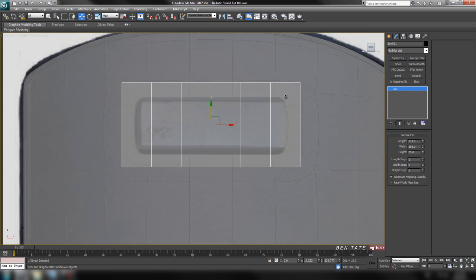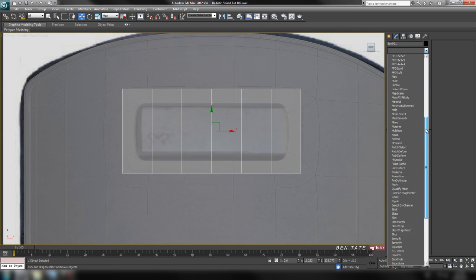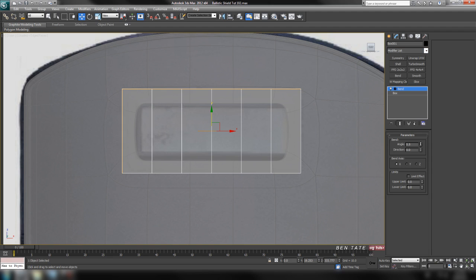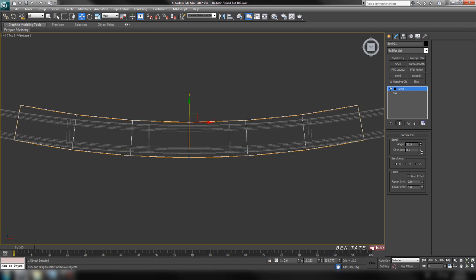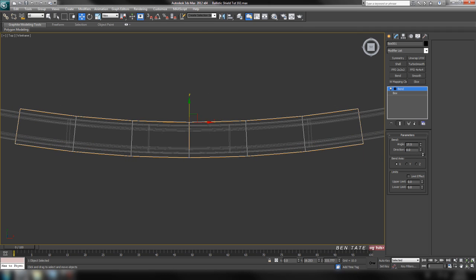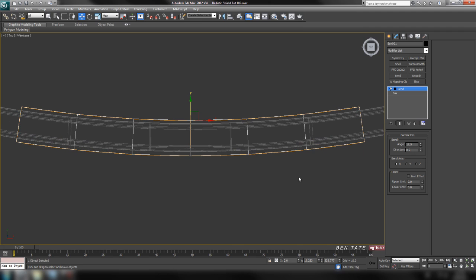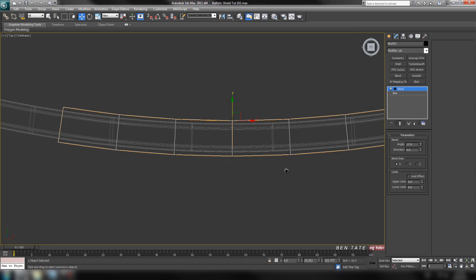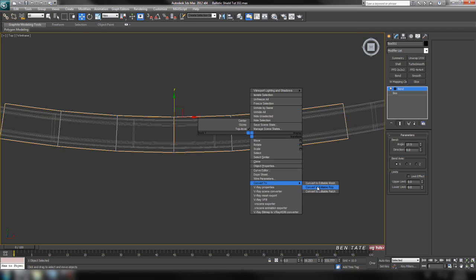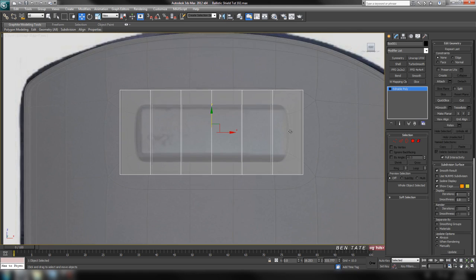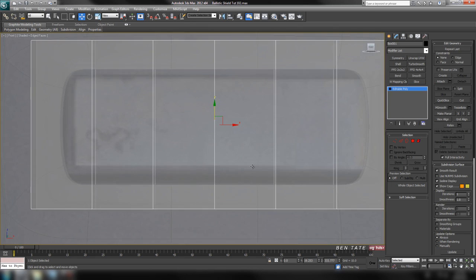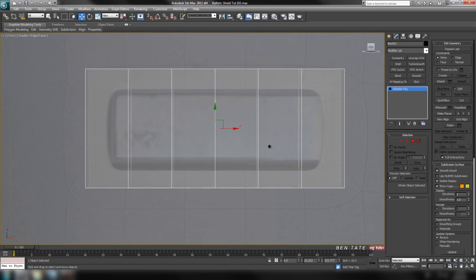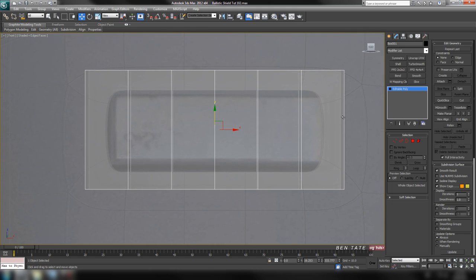And we'll bend it the same way here by adding a bend modifier. Alright, let's grab one of those, throw it on. Do it again on the x-axis, and let's take up the bend amount here. And in the top view, we'll just try to match the curve of the shield. Right, so it looks like about 17.5 on the x-axis is about what we were looking for. Okay, so let's convert that back to editable poly. Go back into the front view here. And I'm thinking that might be a little bit too thick here. We don't want the sides to be too thick.